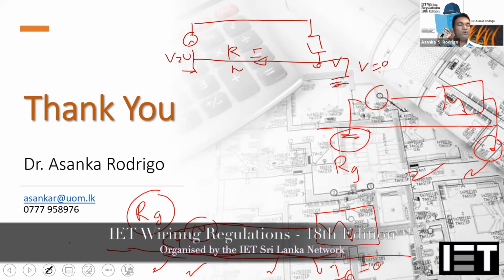Normally, when you look at voltage disturbances, we categorize them into transient voltage disturbances, which are taken care of by surge protective devices. But these are temporary overvoltage or temporary undervoltage situations, which should be corrected by the utility itself. At the consumer level, other than putting in a voltage regulator or voltage stabilizer and maintaining it, it will be very costly when you look at large capacities. The best way is to request the CEB or LECO to do the phase balancing and take whatever mitigatory action is needed for that particular location.